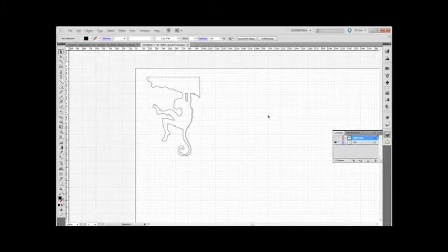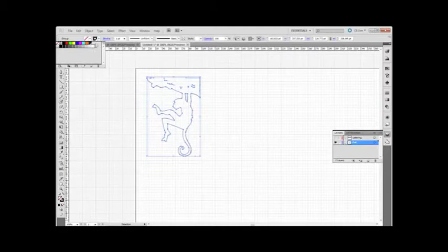What we want to do now is just select our monkey. Okay, the area again, as I said, that we're going to cut, and we can go up here. Right, in here, because we've opened up the laser template, it's got all the colours that we need. As I was talking about, red is the one that we use to cut, so this will go right through the material. So I'll select the red colour, and also the stroke has to be 0.001.